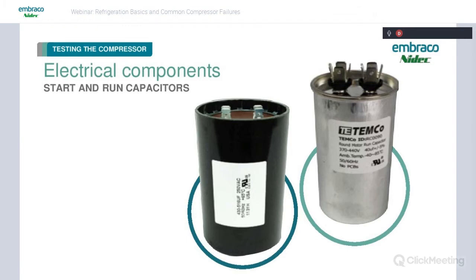So if we have a potential relay where the contacts have welded, you can check amp draw on the start winding of the compressor to see if that start winding is being de-energized. If not, you have to change the relay, and you're probably going to have to change the start cap too, because they get burned up very quickly. They're only meant to be in the circuit for that split second startup time. And then we have the run capacitor.